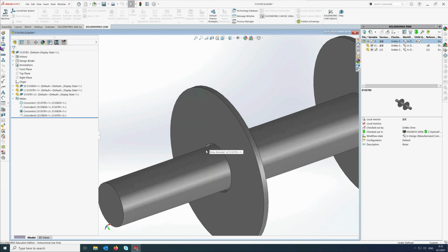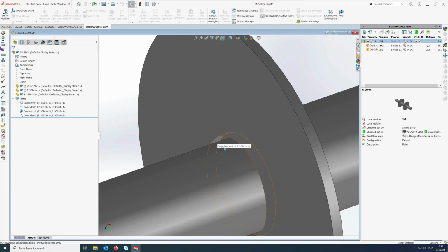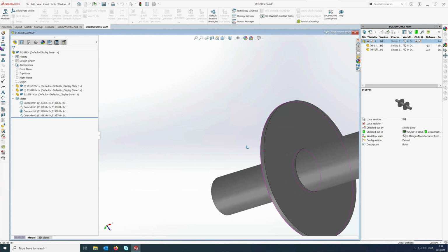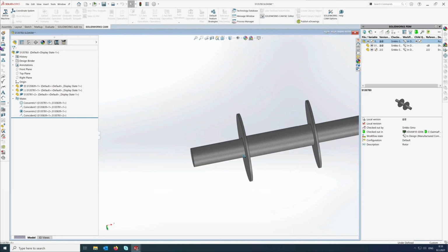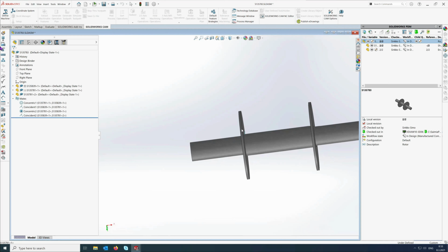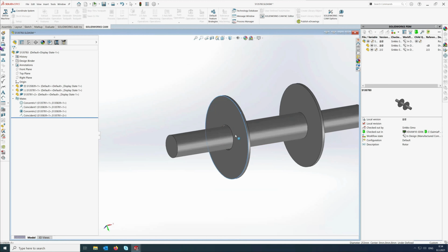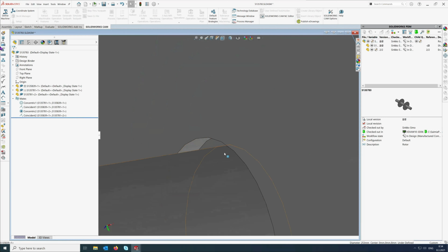And another thing is this hole. So you see now that there is a gap, and I want that there is a gap, because the first step in this assembly is the welding, and I just want that these pieces are very easy to put, and they would slide until they hit this face here, and then a welder is doing the weldment, and it will fill the gap which is here.